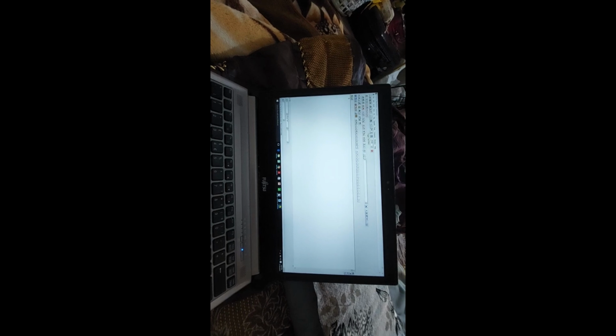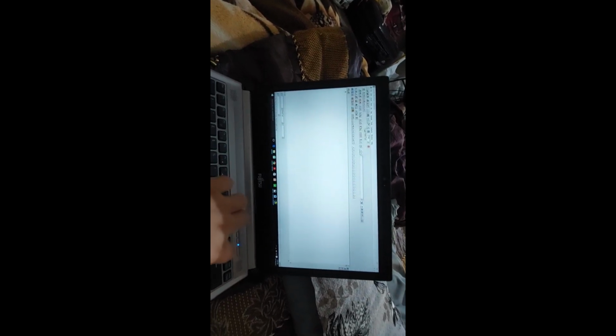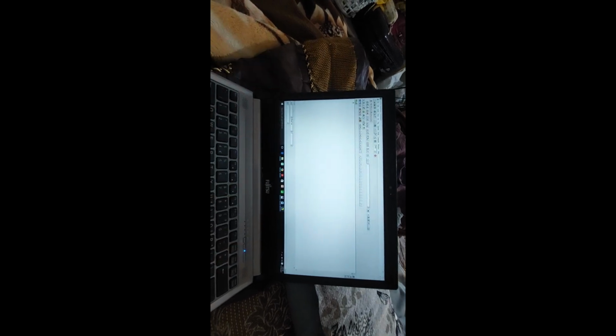So define, and first make it the mathematics. This is t. When I press it, it will go to the mathematics form, and then I press control equal to, and it will go into the definition mode. Now I am defining the problem. So I define f of x1 comma x2, but I must make the x1 and x2 in the subscript.